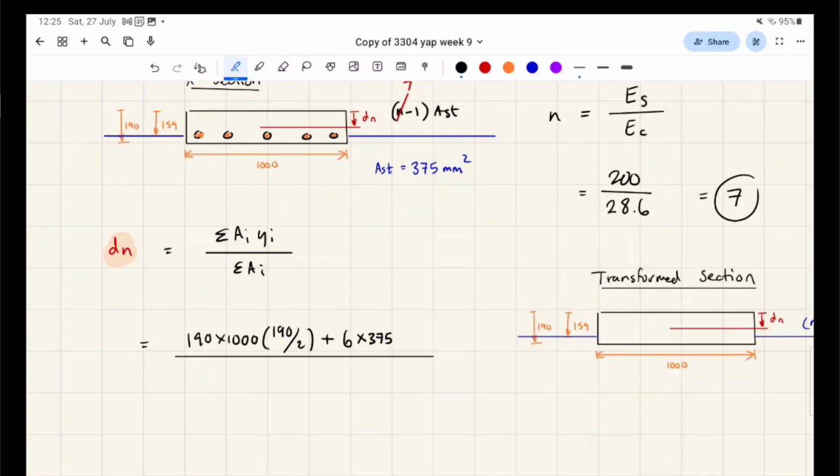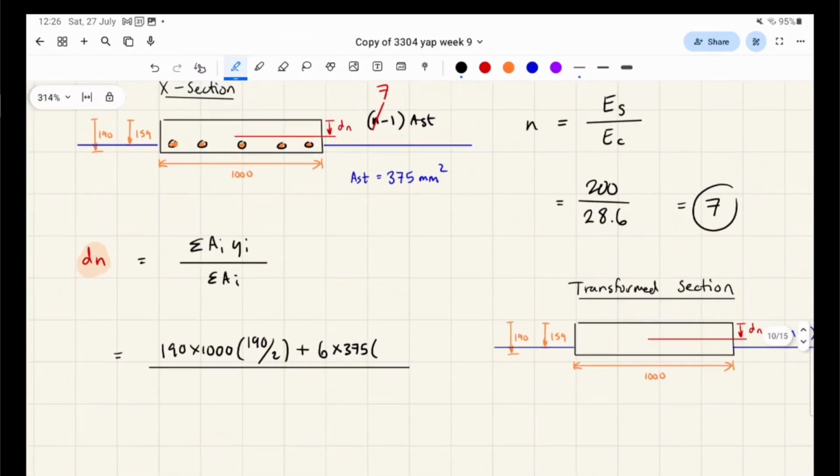I think we've done it in the full workshop, so yeah, it does make sense. Okay, what's the depth to this? What beam is it? Is it N12 bars we're using? Yes. But it shouldn't matter here. It should be 159, because this is already the depth to the middle, right? Before, we were given the clear cover, so you did have to account for that. But since we've already accounted for that, the depth is to the middle of it, so it doesn't matter about the radius anymore.